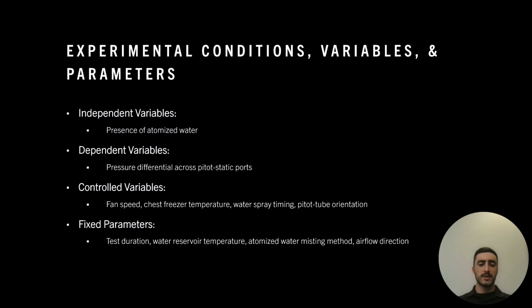For experimental conditions, variables, and parameters, starting with the independent, the key variable we changed was the presence of water spray. This determines whether ice would form and affect the pressure differential. For the dependent, what we measured was the pressure differential across the pitot tube. Changes in this value indicate that ice is affecting either the static or dynamic ports.